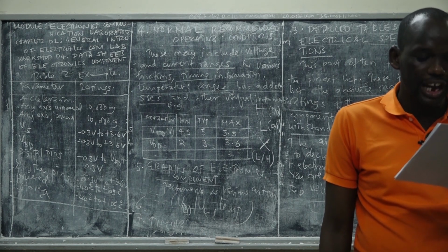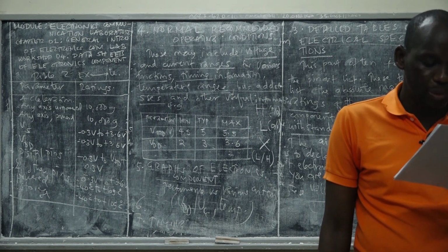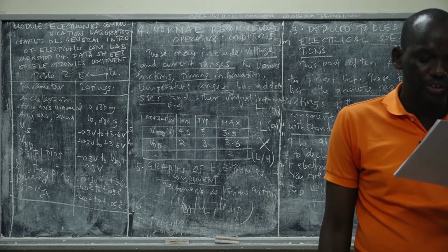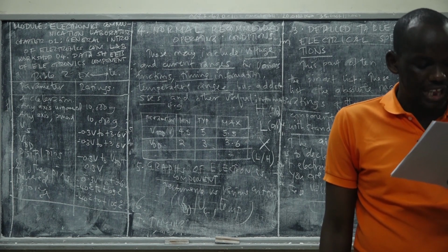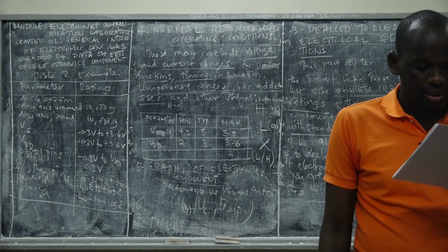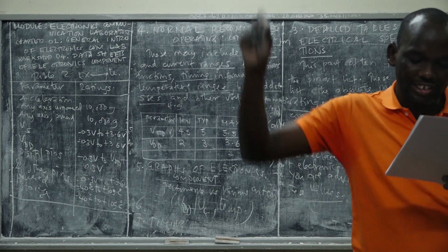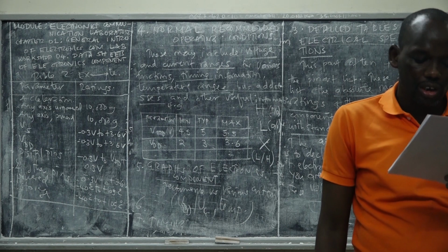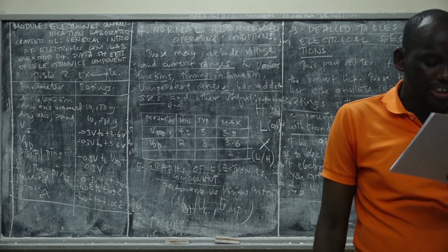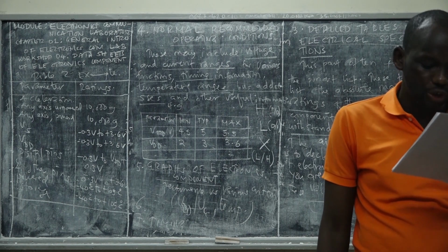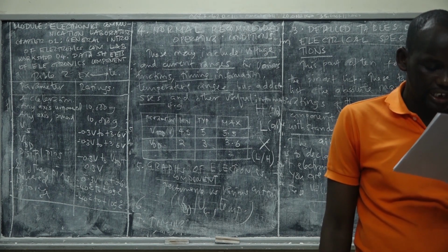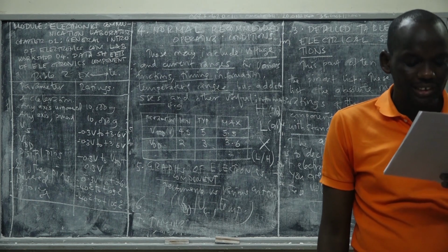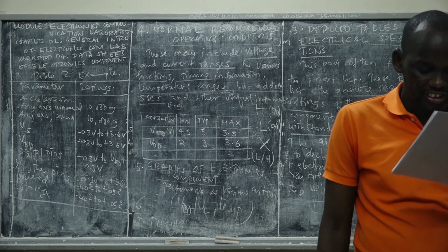These are typically laid out with various inputs and outputs as horizontal lines, showing the logical transitions that happen to those lines over time. If the trace dips down, that is a low input or output. If the line rises higher, that is a high input or output. Timing specifications are laid out as arrows between the transitions. Names refer back to the timing numbers in the electrical specification, and vertical bars or arrows will link the related transitions.